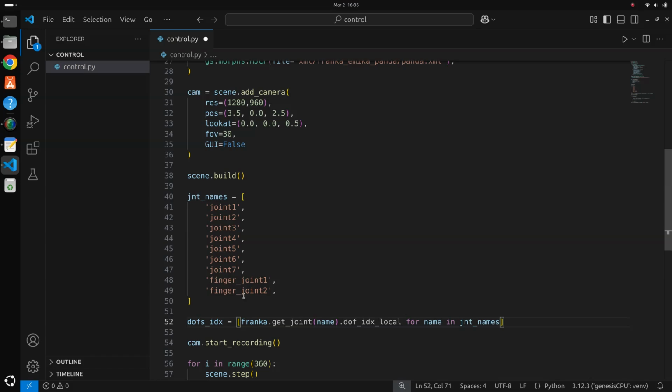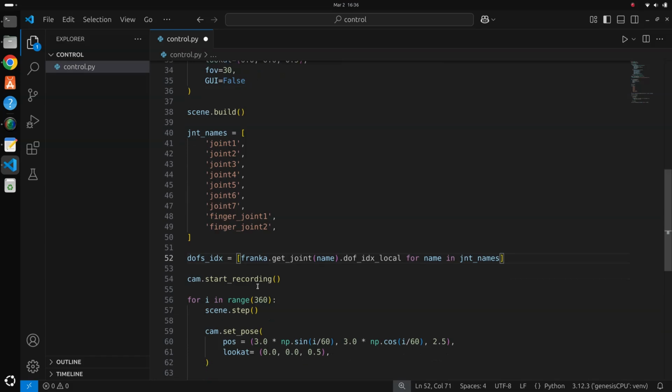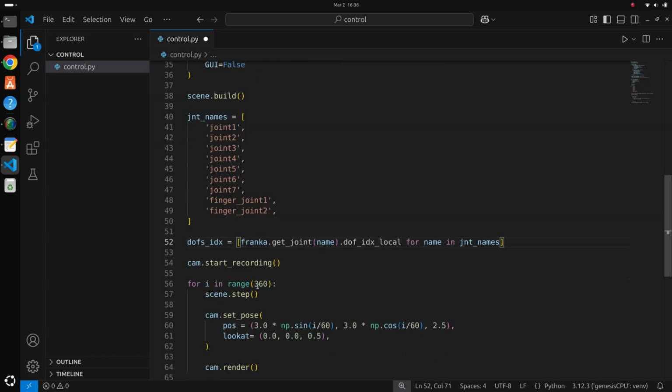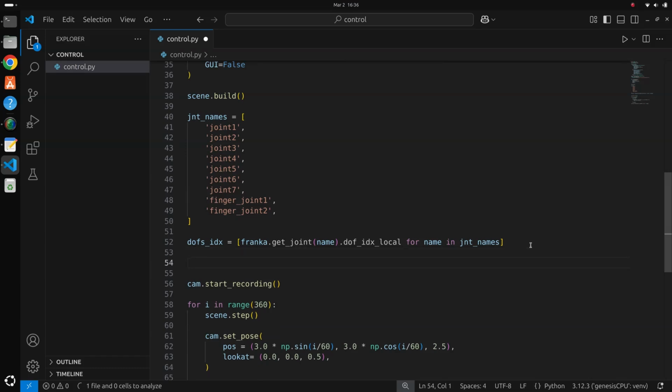When controlling a robotic arm, we want to move its joints to specific positions smoothly and accurately. The controller does this using gains, which are parameters that determine how strongly the robot reacts to position or velocity errors. Usually, this information will be parsed from the imported MJCF file, but it's always recommended to refer to a well-tuned reference value.